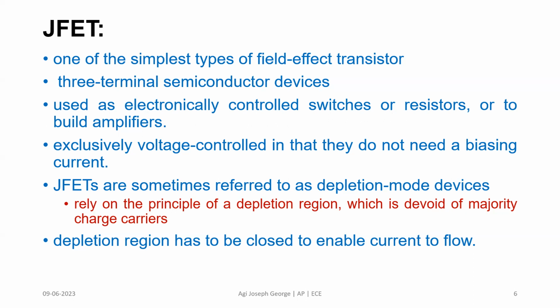Diffusion is nothing but the flowing of something from a higher concentration to a lower concentration. In the same way here, diffusion of charge carriers occurs when the junction forms. Electrons from the N region flow across the junction to holes and they combine. Once they combine, the place where the holes and electrons have left is depleted. It doesn't have any charge carriers. So that particular region is known as the depletion region.